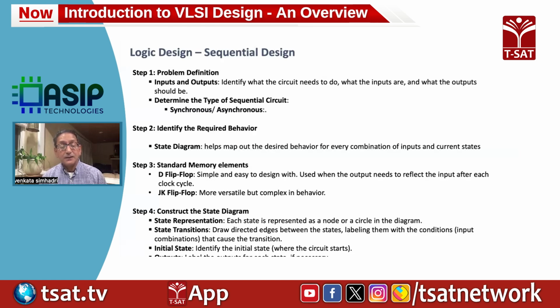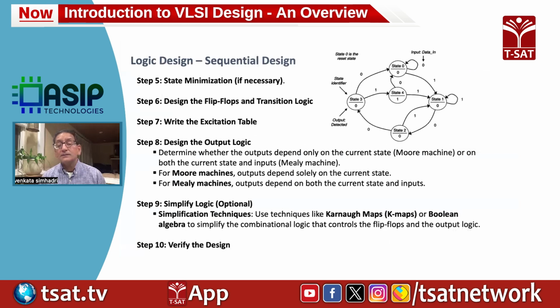And then you get into the actual state diagram. You construct the state diagram by defining what is the state representation, state transitions, what is the initial state and what are the outputs. So this is a simple picture of a state diagram, how it looks like. Then you actually minimize and optimize the state diagram.